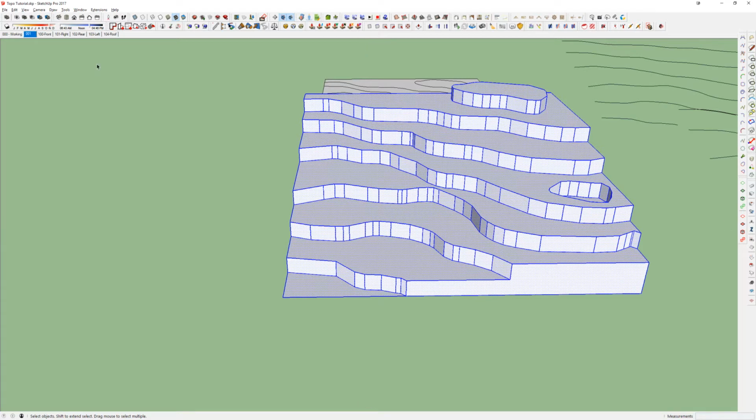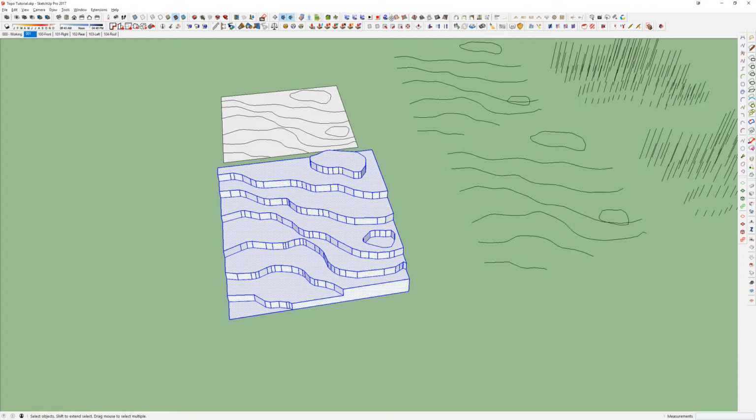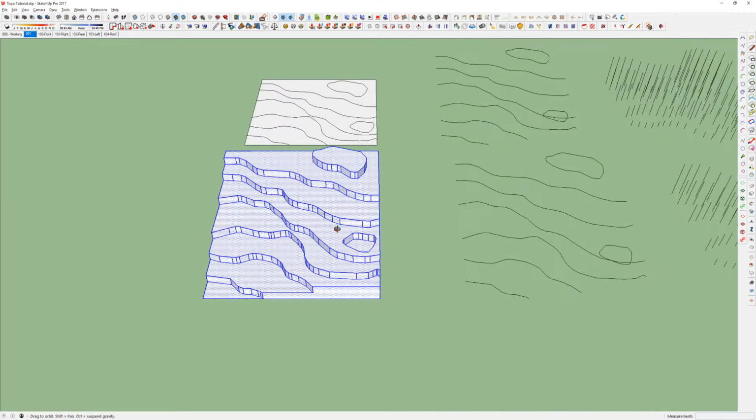So from here, it's really going to be the exact same process. If you don't have them open already, we've talked about them quite a few times, but if you right-click anywhere here on the gray, you should see something called Sandbox, and we're going to use the Sandbox tools. There's a couple other plugins we'll talk about that do it slightly different, and I'll explain the differences. But Sandbox tools is the native one, and that's definitely the quickest, and if you need to do something on the fly, it's a good version. Each one has their pros and cons, but again, we'll discuss it.